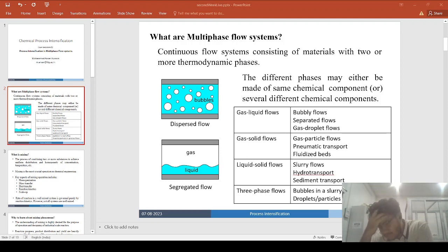So in some cases, for example, when large residence times are desired, comparatively long microchannels have to be integrated into a compact microreaction device, a task that can only be achieved with curved channels. So in the previous class also, what I have just shown you is that by utilizing curved channels, you can exploit the formation of secondary vortices of the curved flow path, such as the Dean vortices, to intensify the mixing.